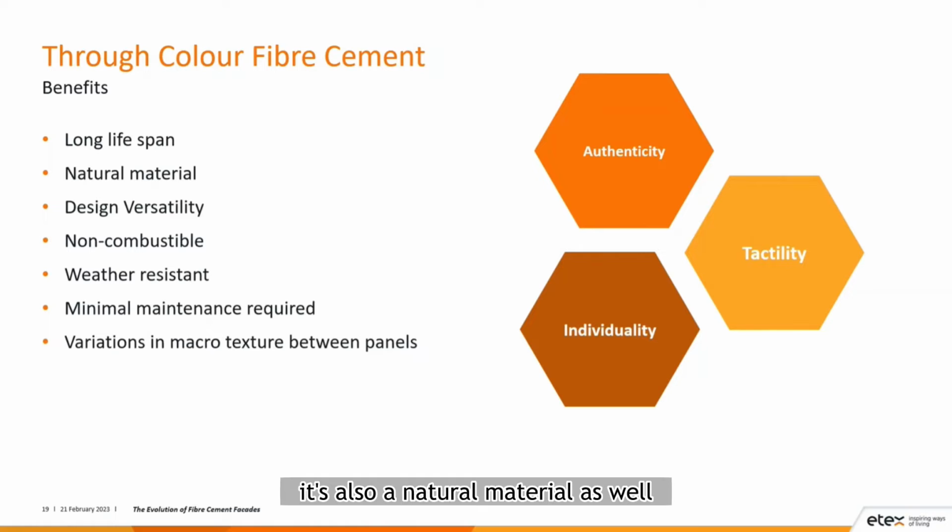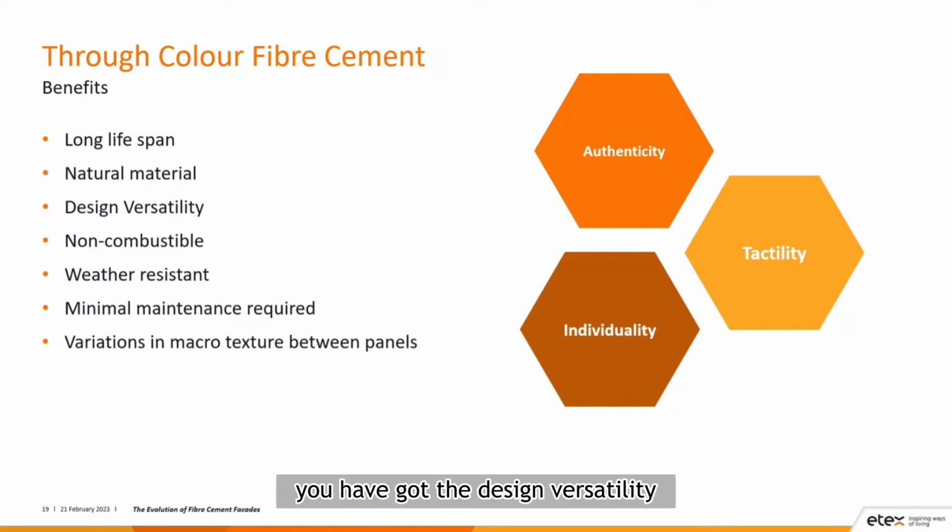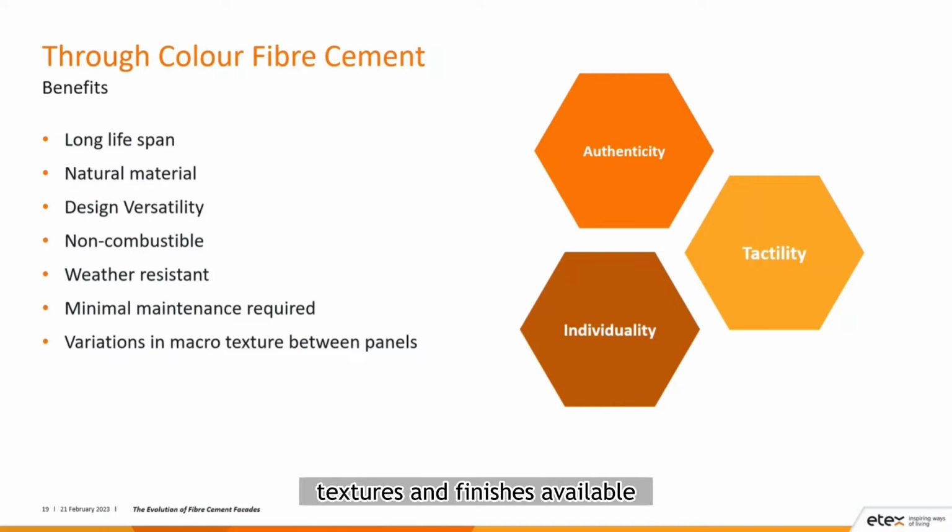It's also a natural material as well. You have got the design versatility through your different colors, textures, and finishes available. It's deemed non-combustible in Australia. So it can be used in areas without having to test the panel for fire and things like that, because it's deemed non-combustible.